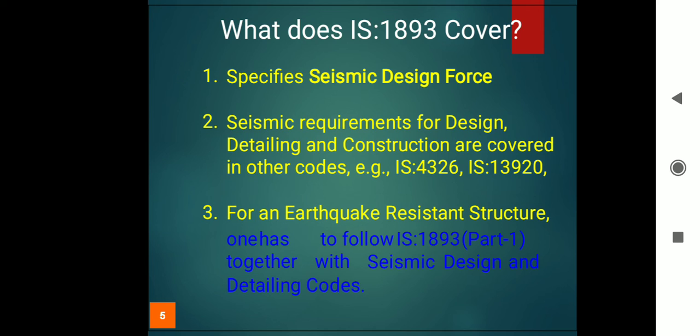The next modification is that this revision adopts the procedure of first calculating the actual forces that may be experienced by the structure during the probable maximum earthquake if it were to remain elastic. Then the concept of response reduction due to ductile deformation or frictional energy dissipation in the cracks is brought into the code explicitly by introducing the response reduction factor in place of the earlier performance factor.